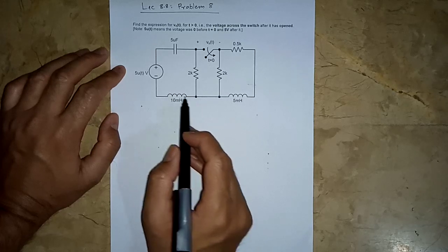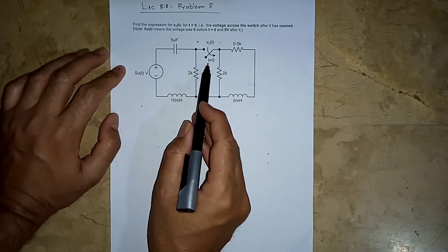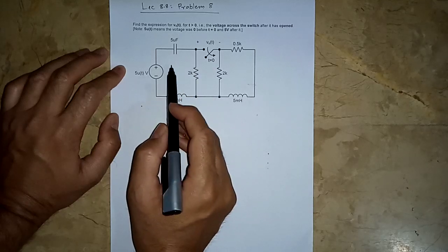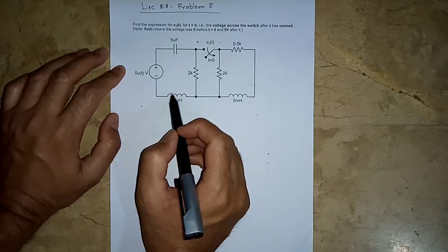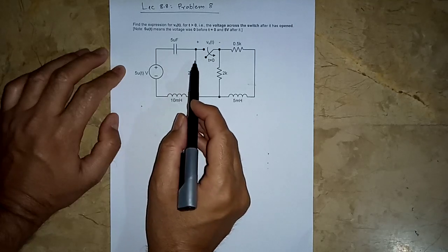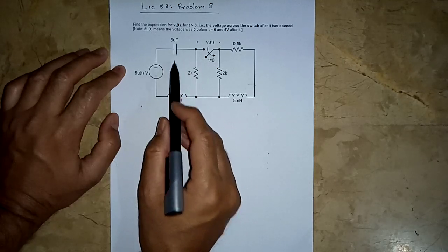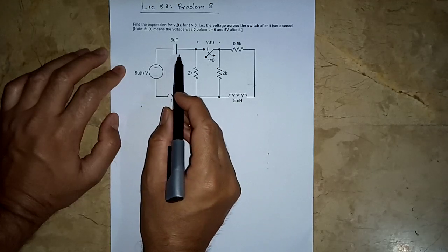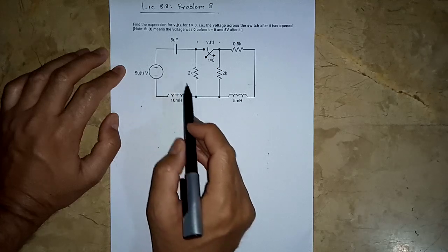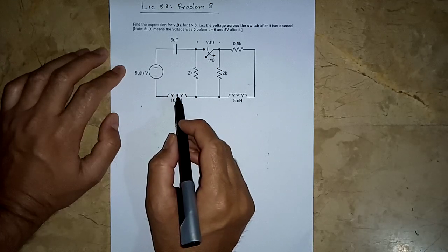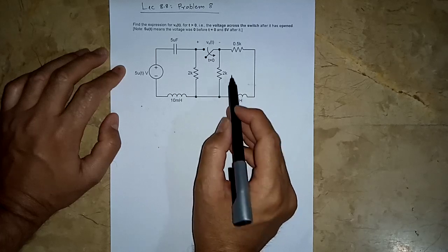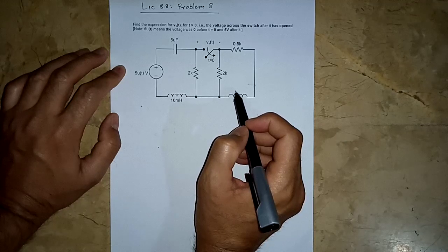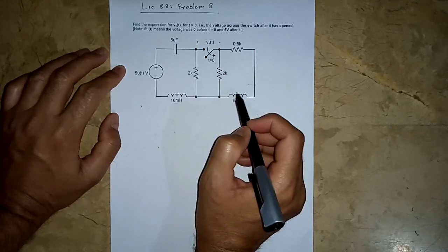And after t is equal to 0, just when the switch has been opened, because there was no energy initially in the circuit, this shorted out, this opened up, and this resistor in there, no voltage across this, no current through this, no current through this. So there will be no voltage initially across this, and no current initially through this. Similarly in this circuit, there will be no current here, so no current after the switch has been opened here as well.